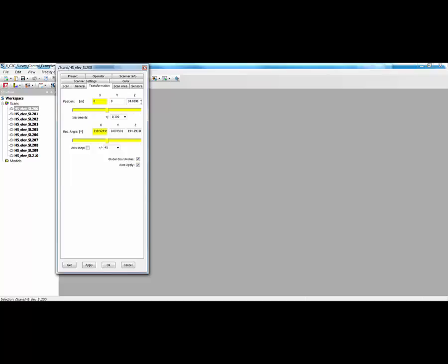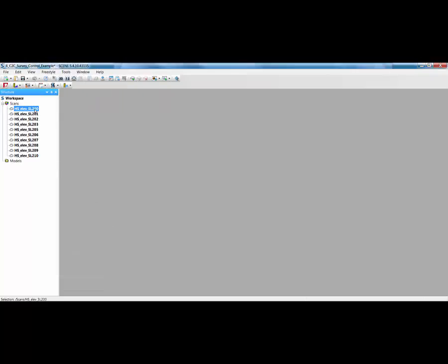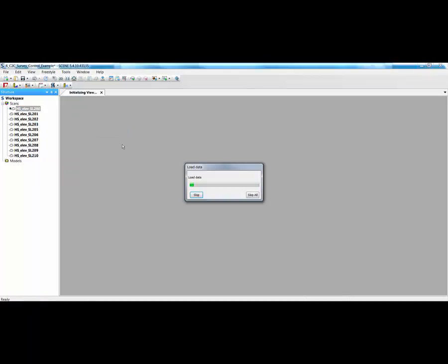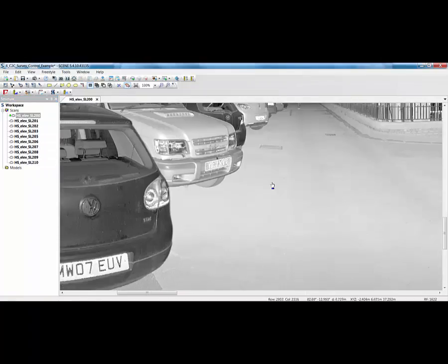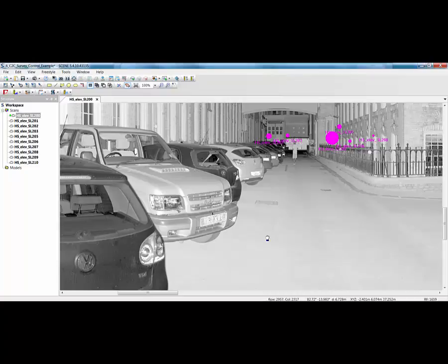This Z value relates to the height of the physical scanner. So if we're trying to set a datum point on a surface, on a floor, on a nail, on a target, we first need to calculate the height of that scanner above that particular datum point. To do this, if I go to the planar view and look at the data first, what you'll see are scans that I've used before when I brought this data in and registered it onto survey control. The data once again is courtesy of Bury Associates in Worcester.